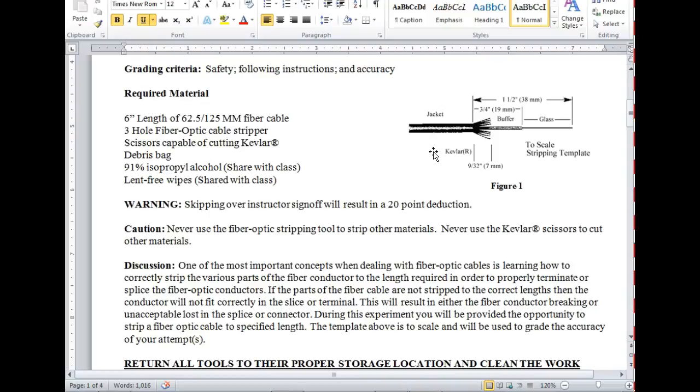Okay, guys, what we're going to do in this lab, I just thought about this when I was cutting these short lengths. It's going to be impossible for you to strip that without the conductor moving out. So what we're going to do, and we'll never, ever do this again, is come up here and tie a knot in the end away from the one that you're working on. Y'all understand why? Because the length is so short. When I start stripping this stuff, what's going to happen? Yeah, the conductor will move out.